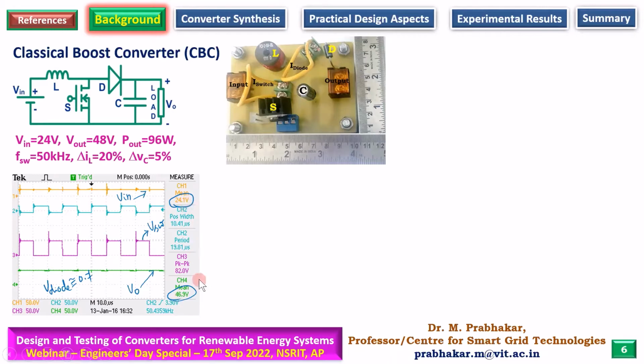We wanted to get 24 to 380. Remember, 380 is our objective. So we thought of pushing this converter. When we operated, let's say D equal to 0.5, we get a voltage gain of 24 to 48. Whereas if we want 380 volts, then our D value should be very, very large. Because remember, V naught by V in is given by 1 by 1 minus duty ratio D. So if D equal to 0.8, then V naught by V in, which is voltage gain, will be somewhere close to 5 times. V naught by V in will be equal to 5. That's what we wanted to test.